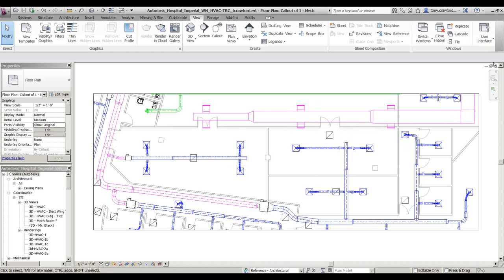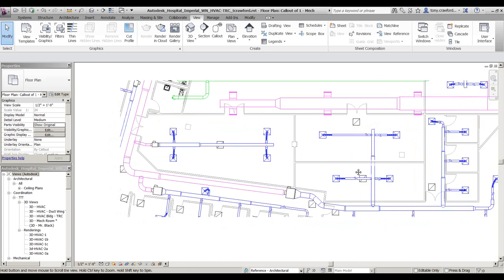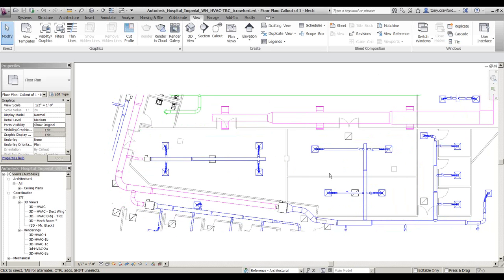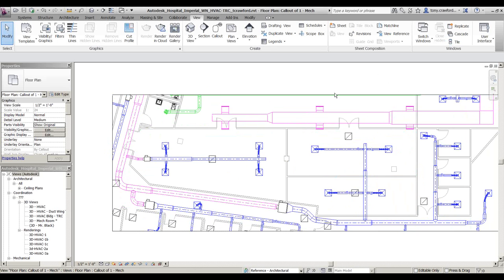He's going to delete that view. That view no longer stays in the file, and it doesn't take up any space when he's done. But while he's working in it, he just works in this one view. You can close his windows. So he's only working in this one piece, not the entire file. So it's not generating the entire floor plan, just this one area.